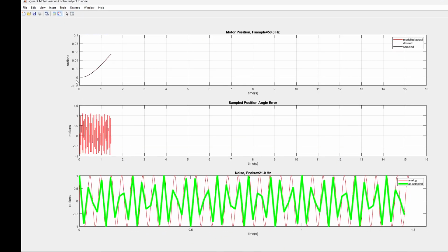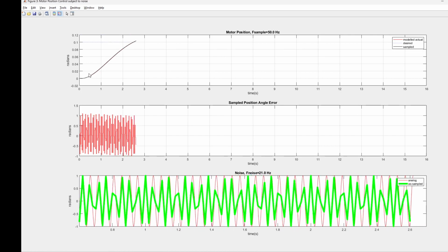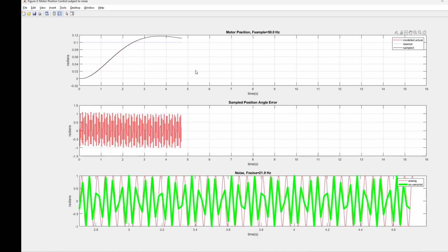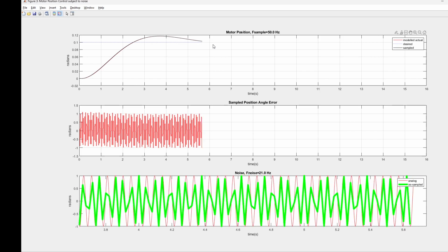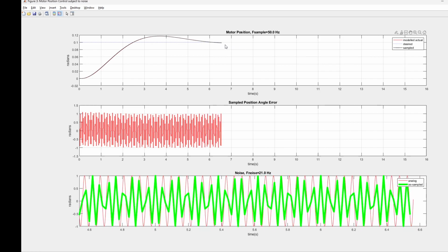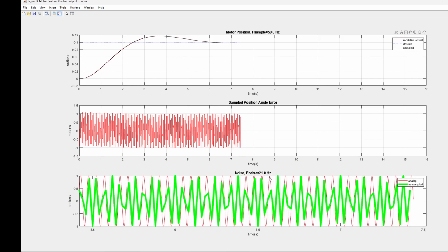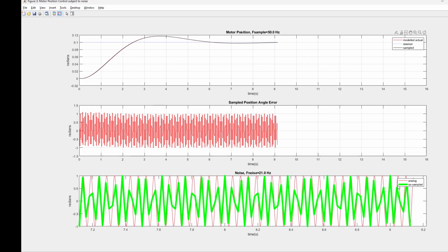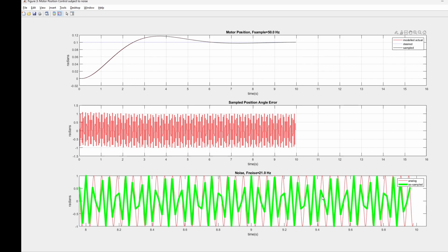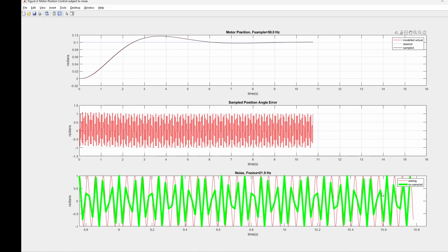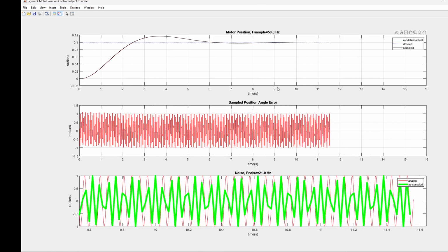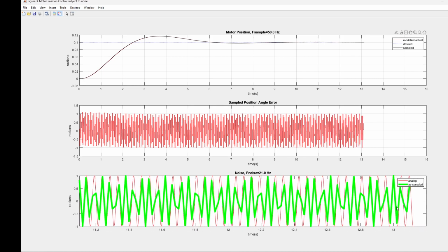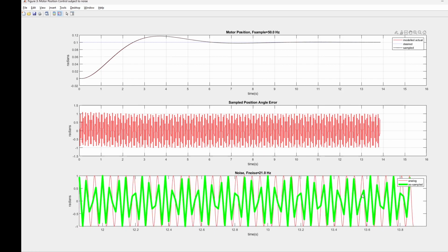In the top graph, we're just leaving from 0 initial condition to a reference, a desired position of 0.1 radian. Again, amplitudes don't much matter, nor does the settling time performance of the controller so much. In the bottom, on a tighter time scale so we can see it, the red sine wave is the 21 hertz noise component, and the green is as sampled. So at 50 hertz, we're sampling 21 hertz of noise faithfully enough to acquire it at that frequency.